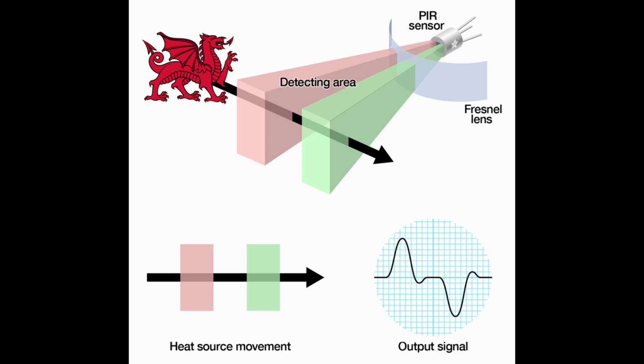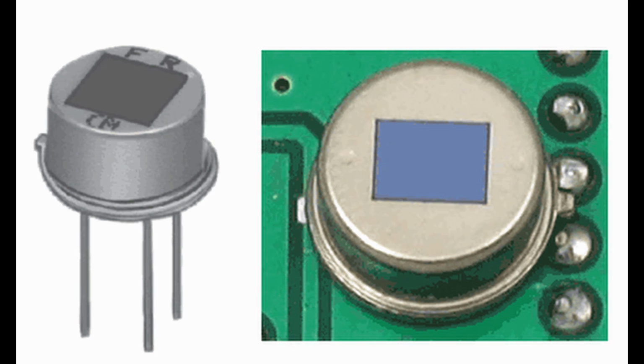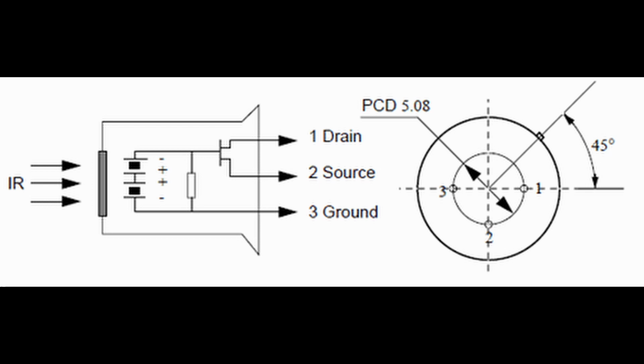The IR sensor itself is housed in a hermetically sealed metal can to improve noise, temperature, and humidity immunity. There is a window made of IR transmissive material, which is typically coated silicon, since it is very easy to come by, that protects the sensitive element. Behind the window are 2 balanced sensors. This image shows the internal schematic.